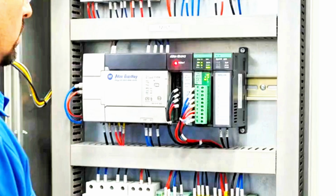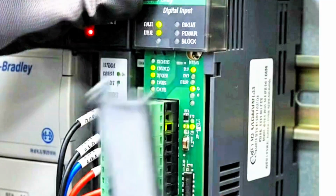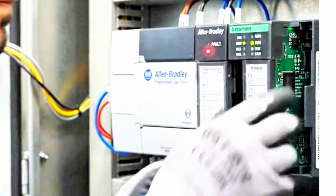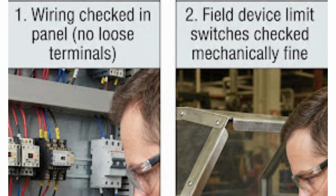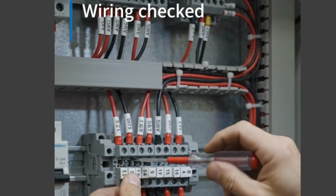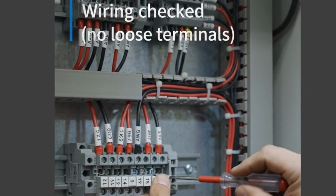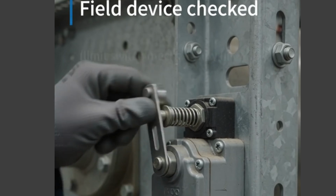own problem. First troubleshooting instinct for a lot of technicians is to suspect the card itself, maybe it's failing, swap it out. We did that early on. Fault kept happening on the replacement card too. So it wasn't the card. Once the card was ruled out, we went through the usual suspects. Wiring terminals, checked and tight, no corrosion. Field device itself, the limit switch was mechanically sound, no intermittent contact issue we could find with a meter.